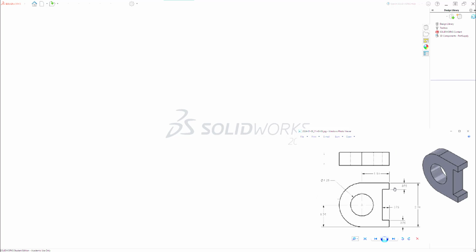Since this has the most complex shape, you can see what it would look like if you were to look from the top, and if you were to look from the right-hand side, you'd see a rectangle here and a rectangle here and a rectangle in the middle, and you'd have dotted lines for the holes. But realistically, the shape itself is a rectangle, so you wouldn't see the arc or the curve on the front edge of the object or anything like that.